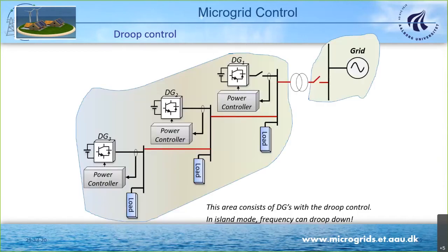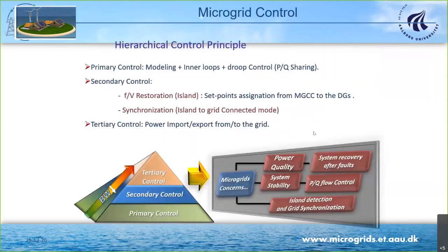Another important thing is what happens when I have a number of power electronics converters connected to a grid, and this grid passes to island mode. Once you pass to island mode, because of these Droop controllers, the frequency goes down. And because the frequency depends on the total amount of generation and consumption, what we need is to establish a hierarchy of control. If you look at big power systems, they use kind of the same hierarchy of control. We have the primary control, which is basically the inertia of the system, which in the case of microgrids or power electronics based systems we have to emulate.